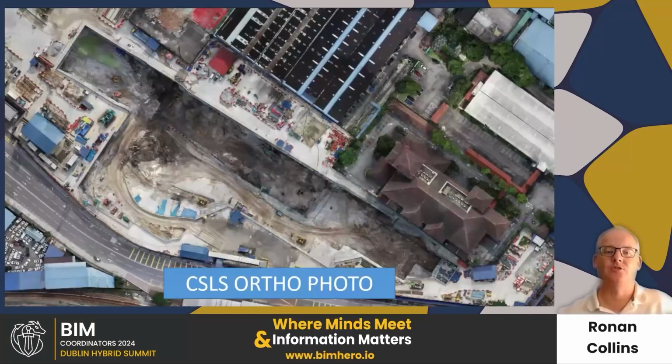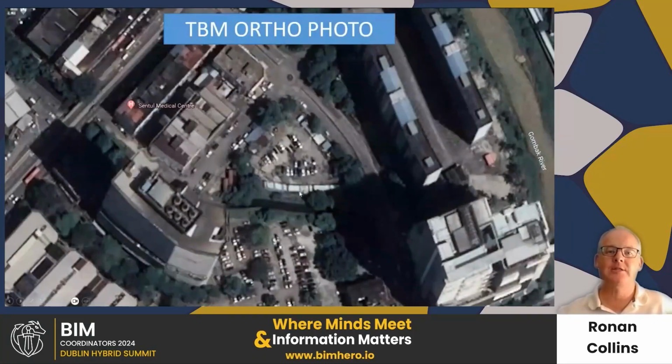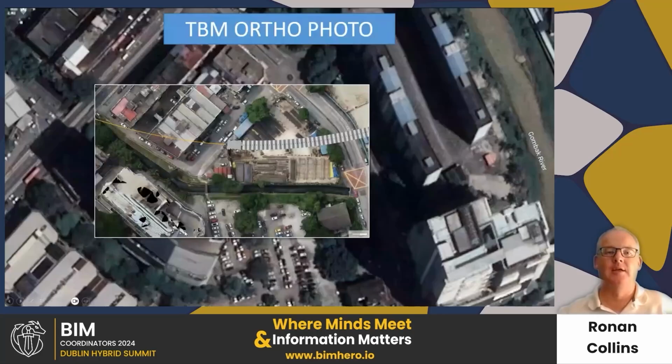And because it's a true orthographic photograph in the site coordinates, it's a very useful way of being able to overlay information. So for comparison, this is a Google Earth image. You can see the lean of the buildings because of the way the images are taken from satellites. This is an ortho photograph of the same area, so you cannot see the building elevations. You see a true orthographic representation of the buildings. And then you can overlay things like tunnel alignments, works areas, access areas. So using drones to create ortho photographs is a very useful tool for the surveyors.